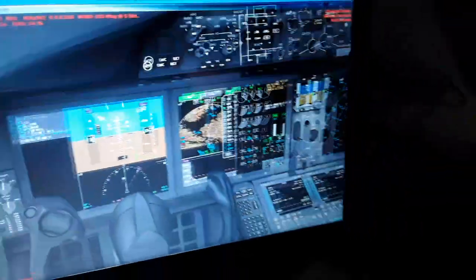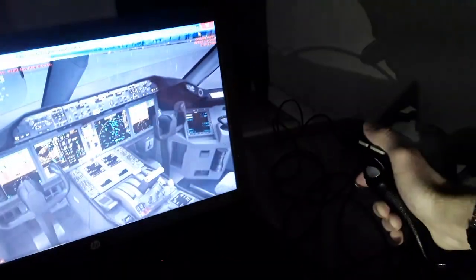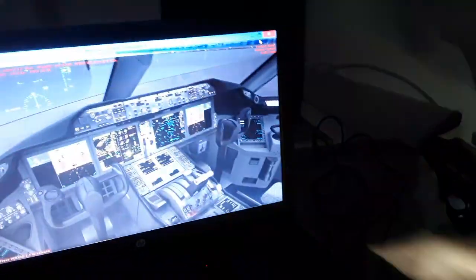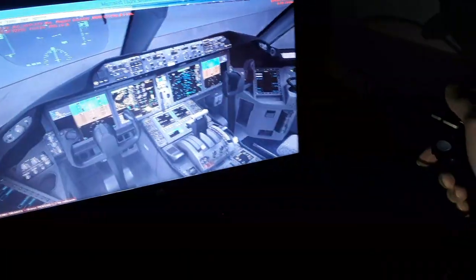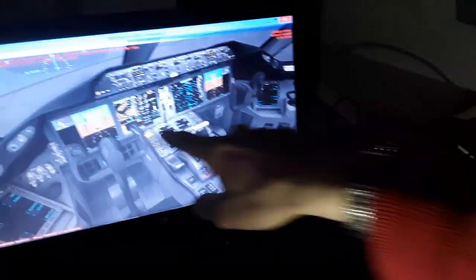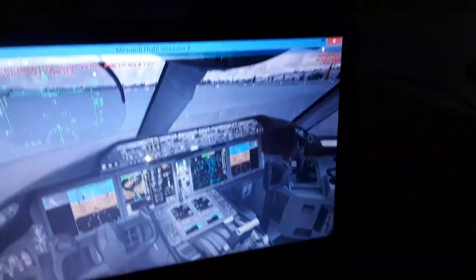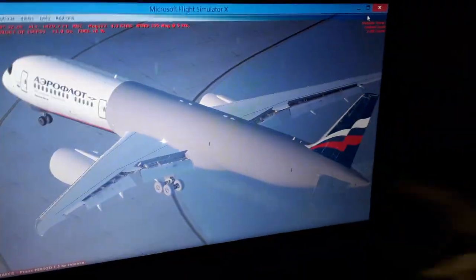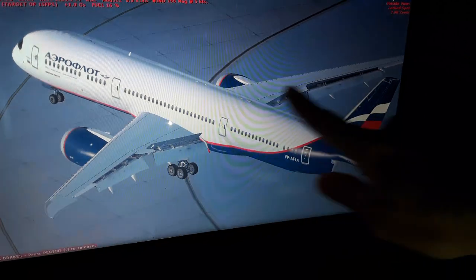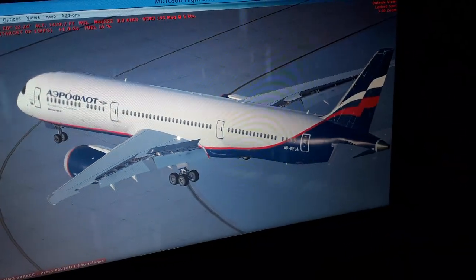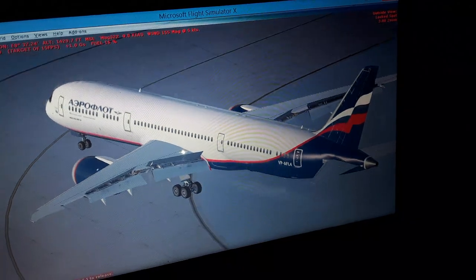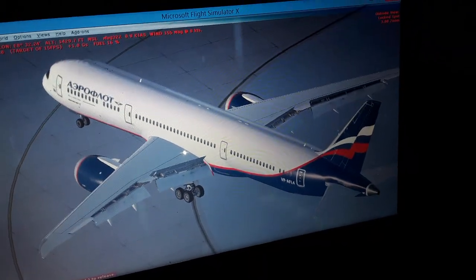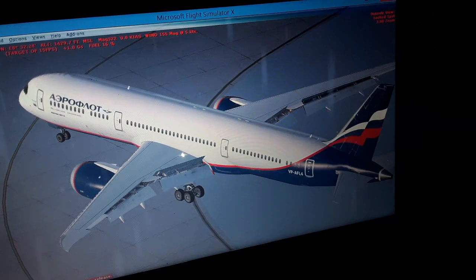So we need to push forward the side stick in the Airbus or the yoke in the Boeing aircraft, and also apply more thrust to make the stall avoidance in the air like this. So you increase the airspeed and you decrease the angle of attack of the aircraft. So this is the angle of stall, it is fixed, and also the airspeed increases and decreases for stalling the aircraft. We need to avoid the stall in the air all the time.